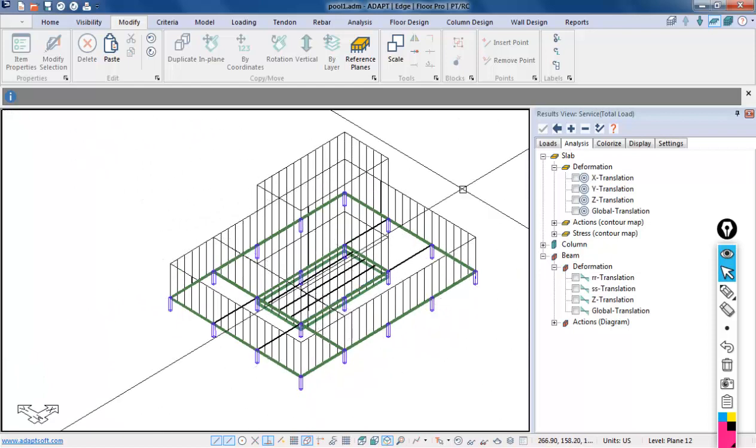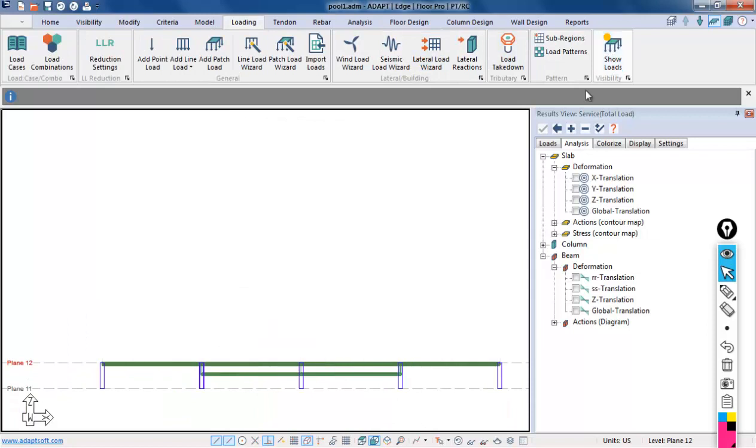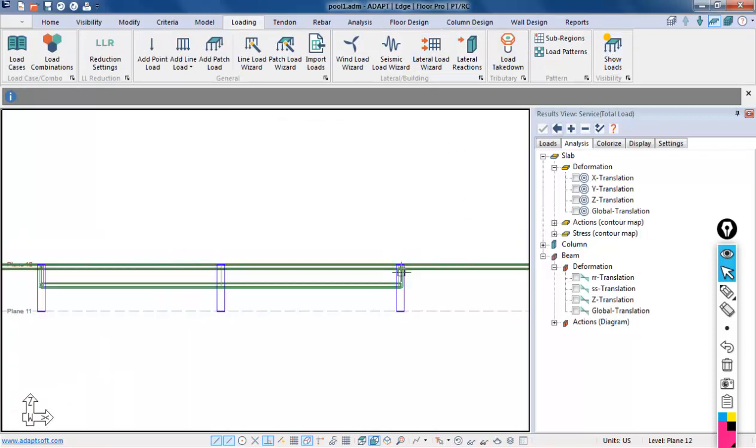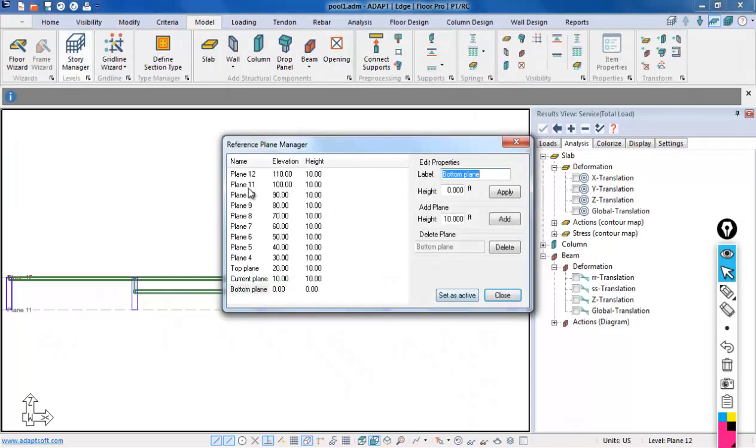Okay, now we're going to change this slightly. The first thing we'll do is generate a short level here. So the level itself is actually going to be just 1 foot below this slab. So this is 58 plus 12, 70 inches in terms of the level. So we'll just say it's 6 feet. And if we go to Model Story Manager, I'm going to say level 12 is only 6 feet, and I'll apply that.